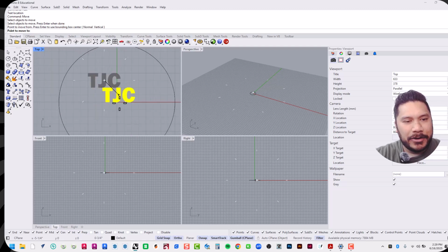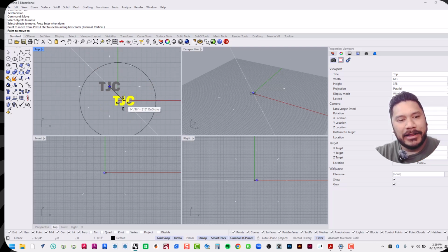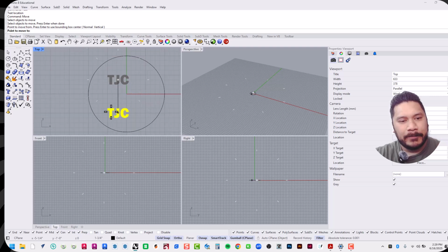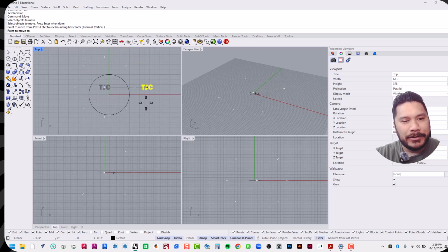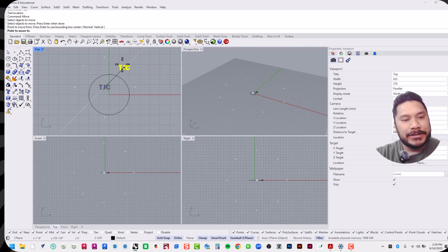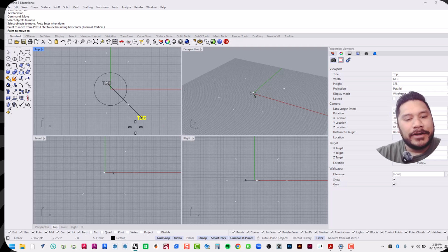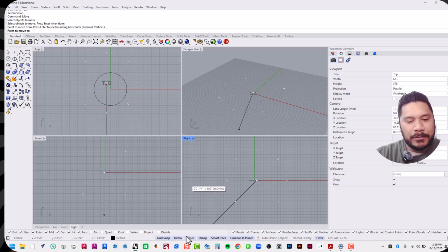elsewhere. Okay. Now notice that as I move my cursor around, I'm not only grid snapping, but I'm also constrained to these very straight movements. I can go left and right, I can go up and down, I can go diagonal, either way. The reason for that is I have ortho on. With ortho, it is going to constrain me to these very straight up, down, left, right, diagonal movements. With ortho off, I can now move to whatever degree or radian that I want.